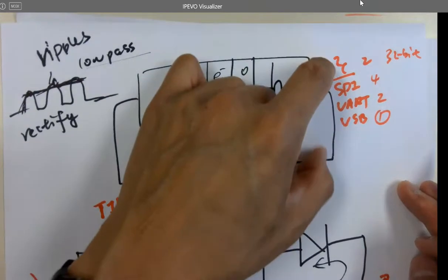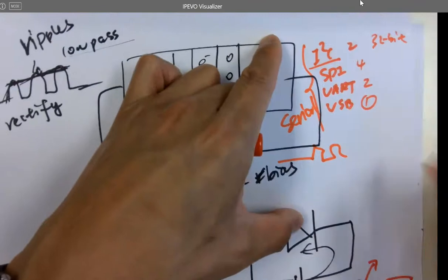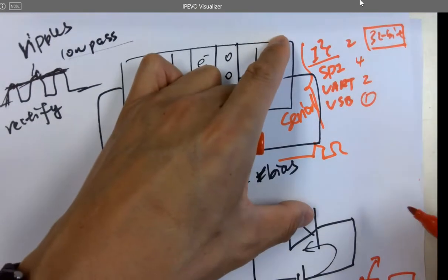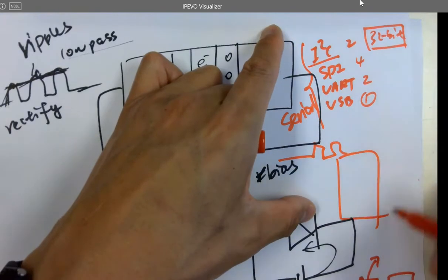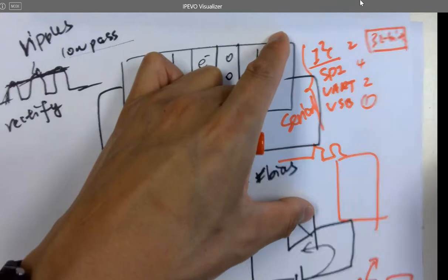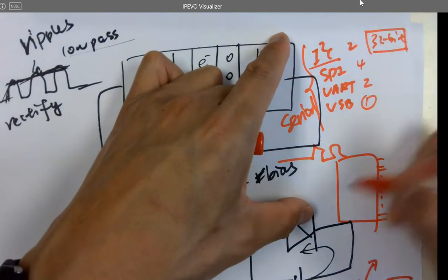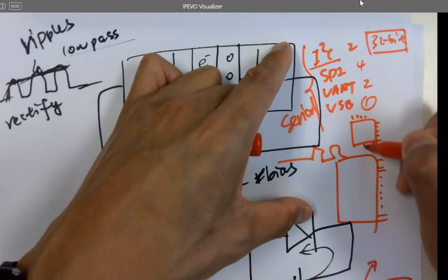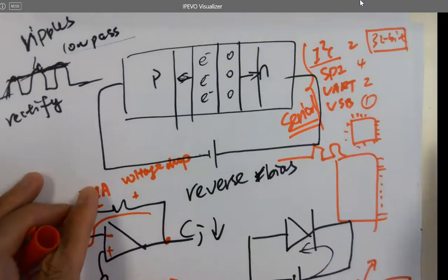All these are serial, which means it's just one line and follows a protocol. If you don't do serial for 32-bit data, if you do it parallel, how many pins do you need? 32. Yeah, one more for the clock, right? I got 32 pins just for sending that data, but nothing else. It's going to occupy all the pin resources. So your die is only this big, right? I only have 33 pins. I can only do that kind of communication, but nothing else. So that's why you want to do serial, not parallel.